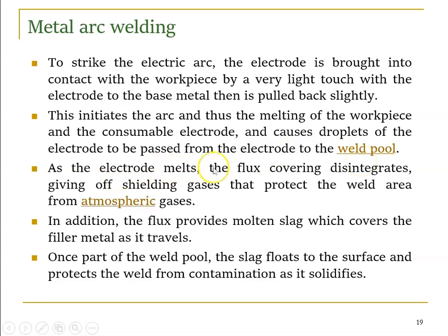As the electrode melts, the flux covering disintegrates, giving off shielding gases that protect the weld area from atmospheric gases. So we use some gases to prevent oxidation. Generally we call it shielding. Shielding means covering or protecting. Shielding gas.